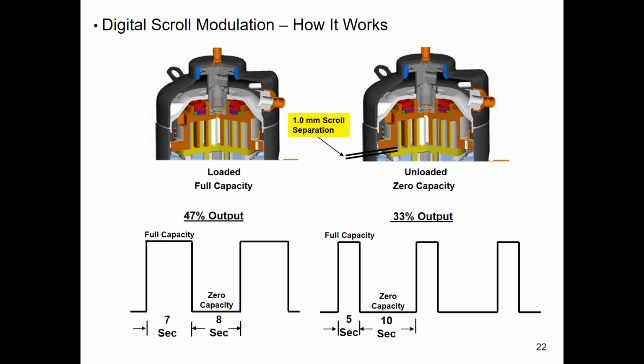If the unit would start up and run and you never shut it off, well, then it would survive because we're always pulling vapor through that suction line. But it's off cycle where the potential damage starts occurring. Yeah.